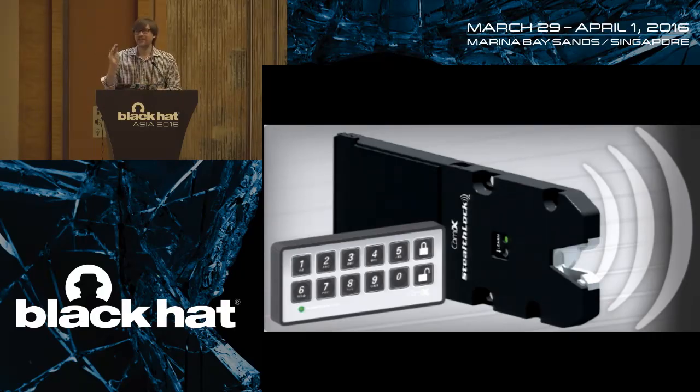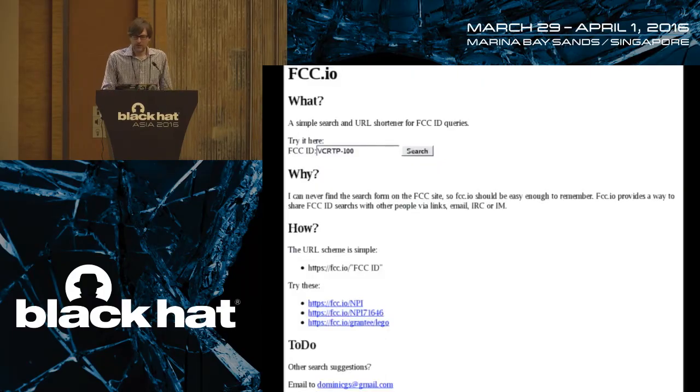When you put the battery in, it doesn't immediately transmit. It doesn't transmit until you enter in a PIN and then press the lock or the unlock button. So while you enter in a number, which is a 4 to 8 digit number, it doesn't actually transmit. But then when you push the lock or the unlock button after entering a number, that's when it transmits. So it seemed to be pretty straightforward. When I press the lock, it should be sending that PIN with a lock code, and when I press the unlock button, it should be sending that PIN with an unlock code. And ever since we fixed that, this device has worked just fine.